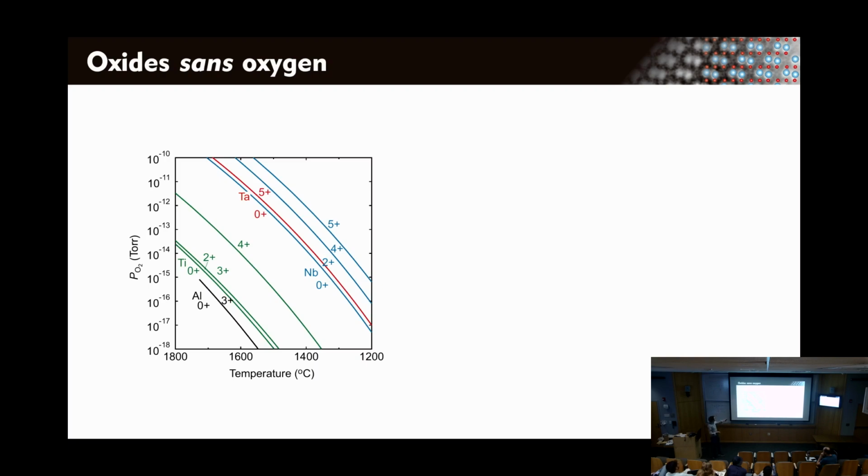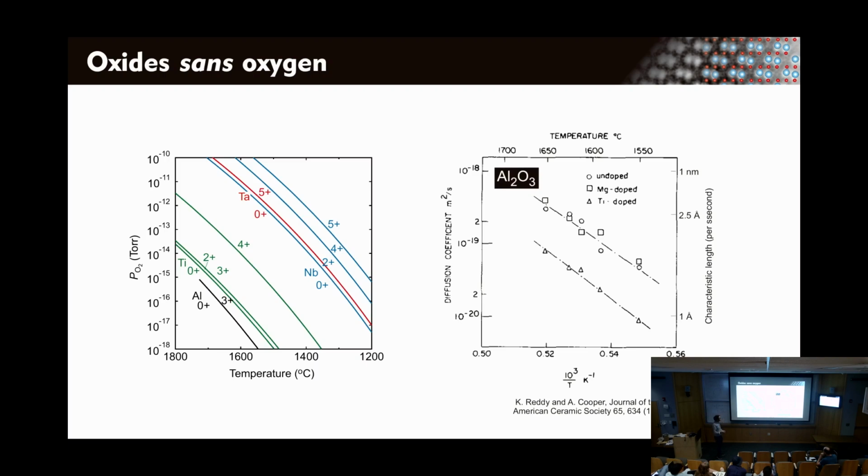So this is some partial pressure of oxygen, which you may think you could open a valve on your chamber and inject oxygen, and that's true. But we found there's other ways to get oxygen into this crystal growth pathway. And this is through what we think is diffusion. Now, diffusion, again, is not something particularly exotic, but it's not something you think about very often when you're dealing with sapphire, because the diffusion coefficient here of sapphire is very, very low.